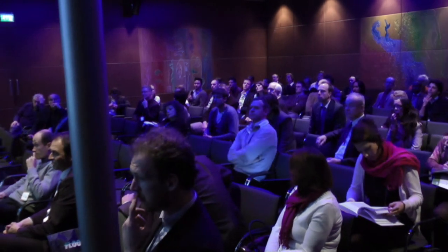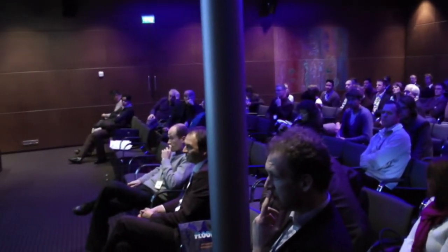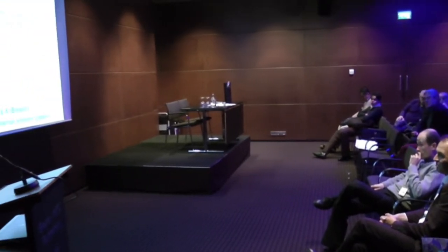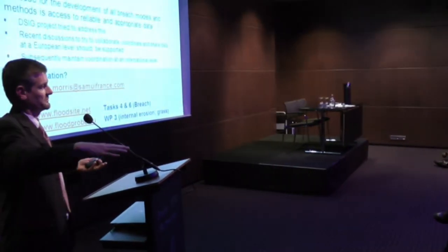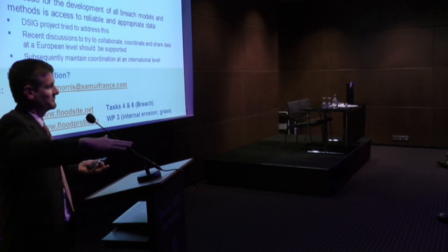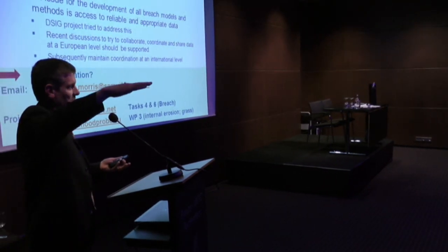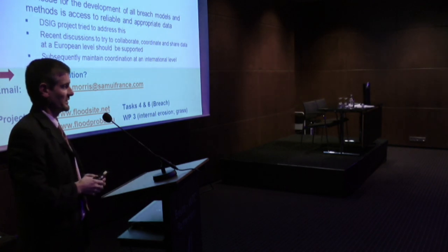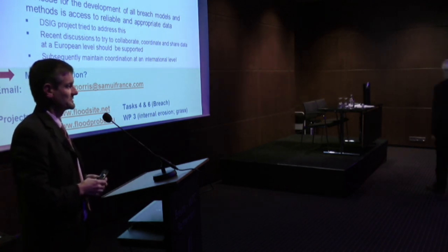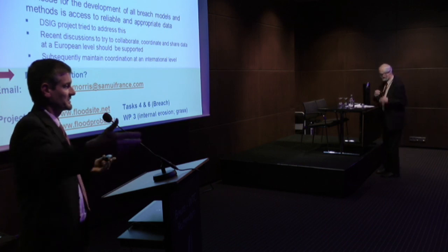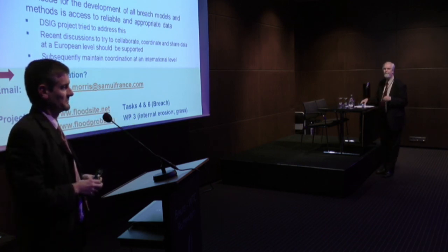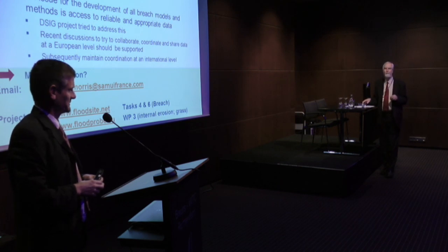Yeah, it depends how you use it. With HR BREACH, you can either have it as a standalone where you simulate the entire reservoir. It's a flat pond model, but it allows you to draw down the volume of water, or you can have it integrated within a flow model like InfoWorks 2D, and therefore it's taking whatever water is being simulated in the flow channel. Is that your question, or did I miss the point?